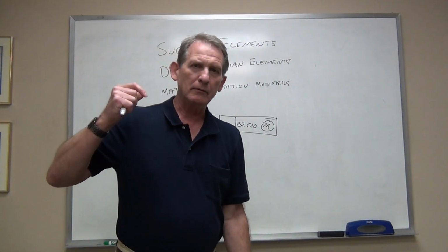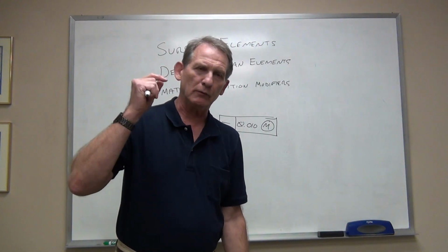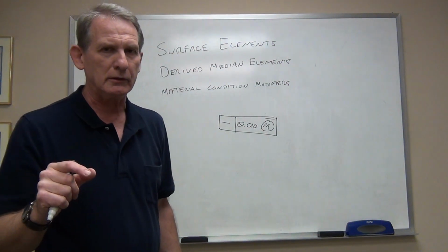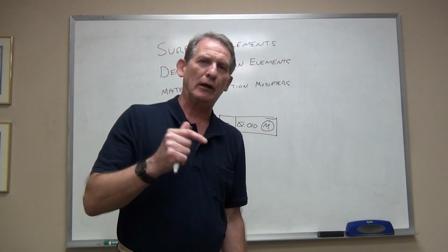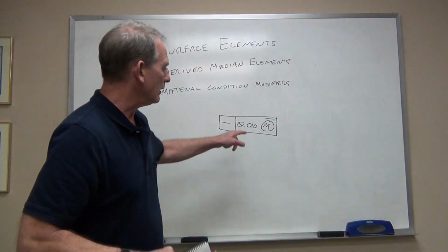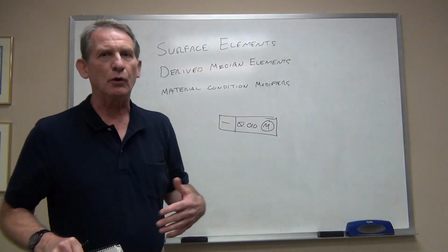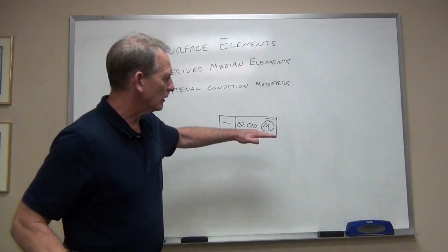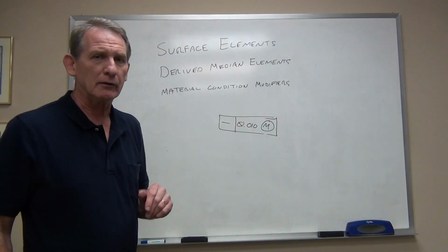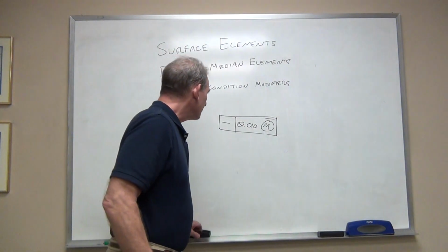As I get smaller and smaller from one part to the next, as that diameter goes down from maximum material condition, I get to add on a thousandth for thousandth basis additional size to this. So this 10 thousandths only applies at maximum material condition. And that's the way you always interpret the material condition modifier in the feature control frame.